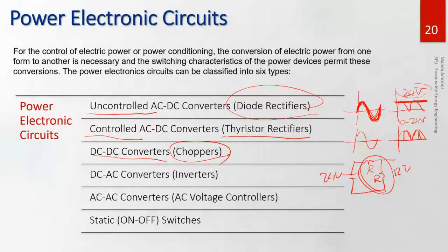Sometimes you have to basically give this voltage divider circuit 10 times what your circuit requires, which does not make sense. So you can't bring down the voltage using a voltage divider. Instead, we need a better solution that these DC-DC converters give us.